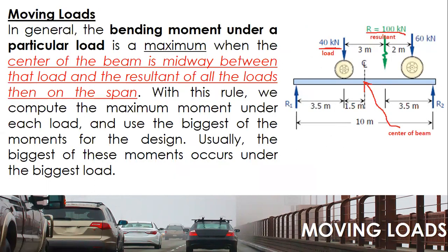So in general, the bending moment under a particular load is a maximum when the center of the beam is midway between that load and the resultant of all the loads then on the span. Okay. You have to master this one.